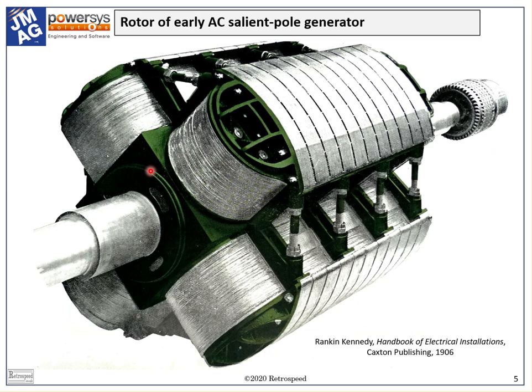This AC synchronous machine rotor carries a DC field winding with exactly the topology shown in the overview. It even has the same number of poles, 4, as we can see by counting the wound projections or salient poles on the rotor. We can also see on the far right the ultimate source of the field current, the rotor of an exciter mounted on the same shaft.